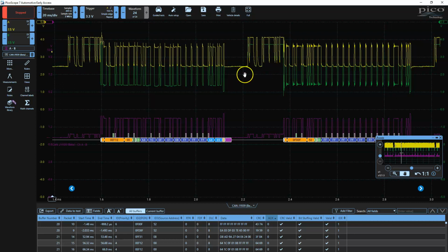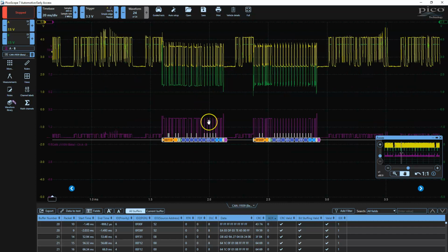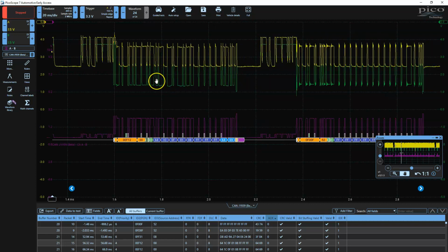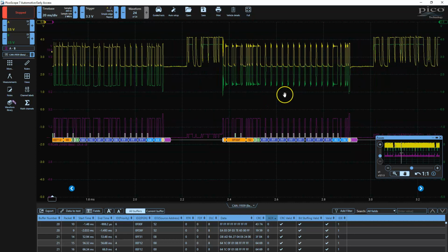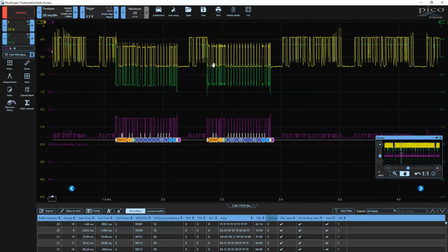And we know that because of the acknowledge bit, everybody else is happy with this message because the CRC is apparently being calculated correctly by everybody. The message is fine. This message from the engine controller, this message from the knock sensor. Really, the only complaint we would probably have on this bus, we might have a few occasional errors, but for the most part, the only complaint we'd have is some complaint about the fuel pump.